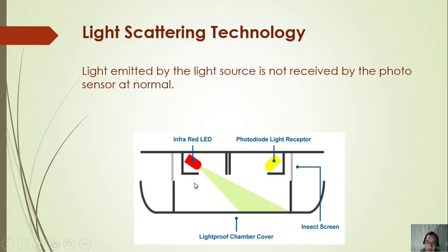But once smoke enters this detector head or the chamber, some of the light will be reflected to the photosensor. Once the photosensor receives that light, it will automatically raise an alarm when it reaches the programmed alarm threshold.